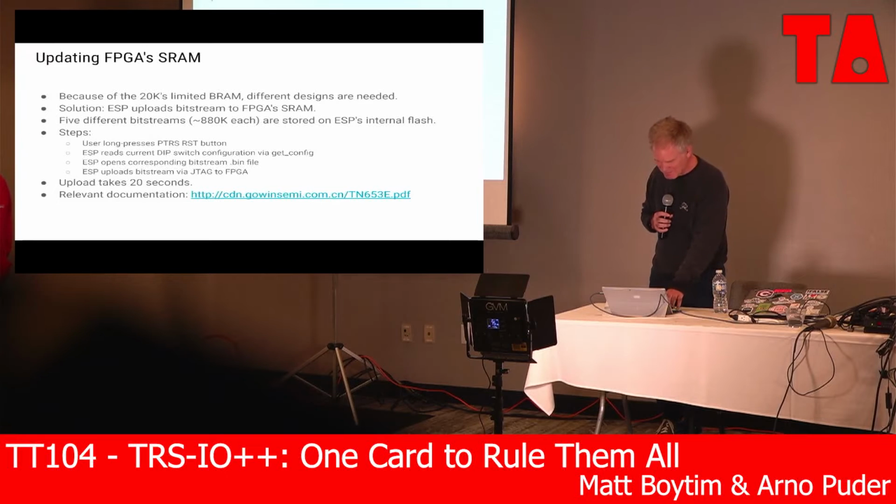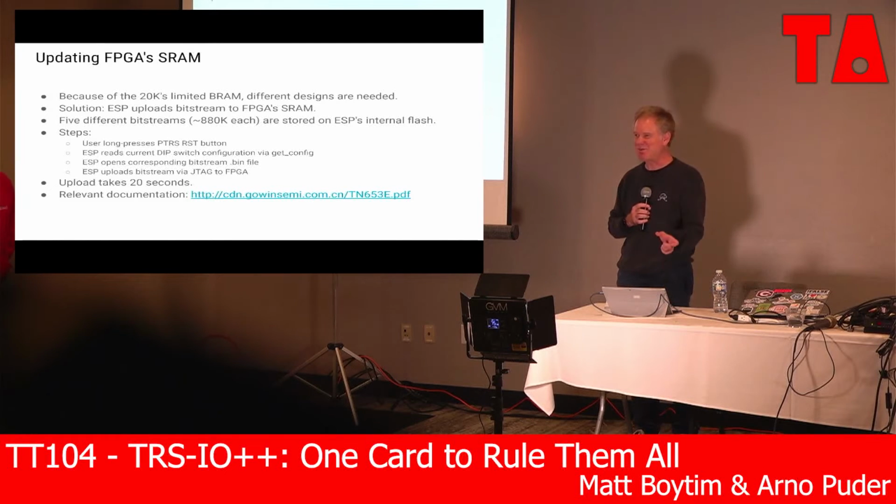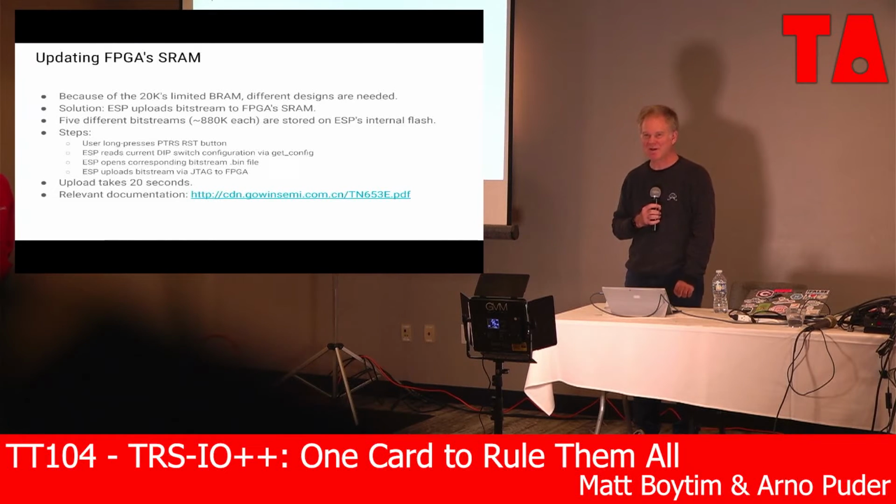One bit stream is about 880K, which also means we need an ESP version that has enough internal flash memory. But there are some 16 megabyte versions that can easily cover this.